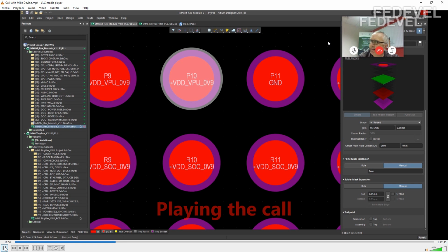Yeah, there are several white papers on that. If you're using an epoxy fill, the resin is of the same makeup as the resin used in the prepreg for bonding. Obviously, if you go for a solid copper fill, then you've got a different thermal coefficient, with the copper expanding at a different rate to the FR4 dielectric, the prepreg, and the cores.